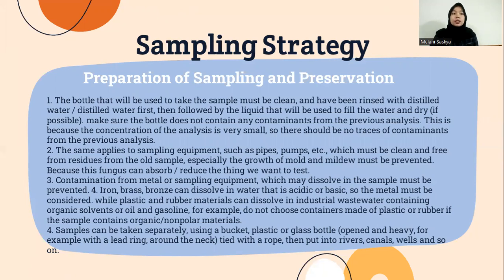This is because the concentration of the analyte is very small, so there should be no trace of contamination from the previous analysis. The same applies to sampling equipment such as the pump and bench, which must be clean and free from residues from the old sample, especially the growth of mold and mildew must be prevented because these fungi can absorb or reduce the thing we want to test.